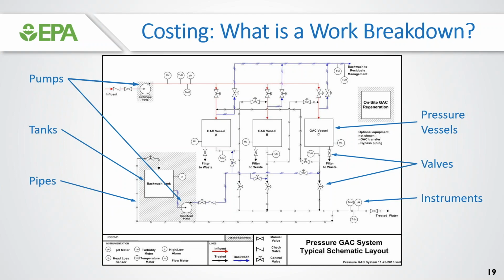Basically, we take all of the different components, the vessels, the valves, the instrumentation, and make predictions about the size of the structure that would be needed for that type of approach. We have costs that are routinely updated to give a prediction: if a plant is a certain size and has a certain throughput, what would that look like on the costing side? That helps from the regulatory side to understand the cost of regulating.